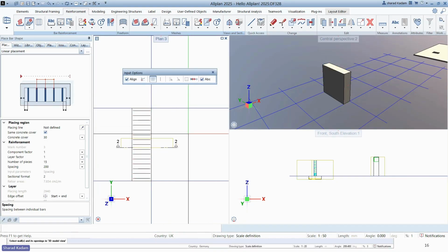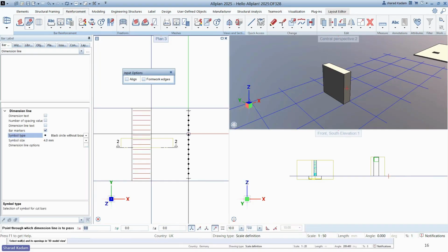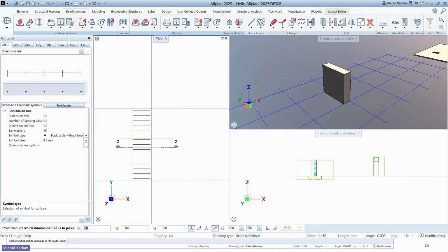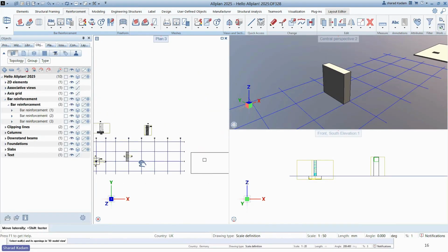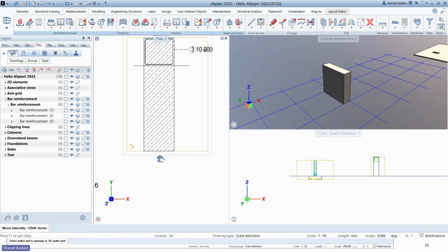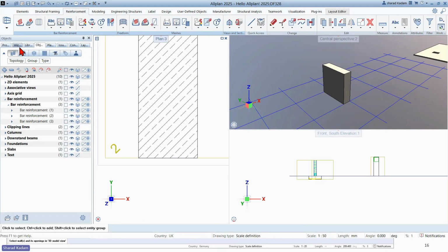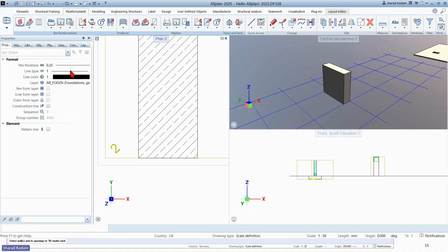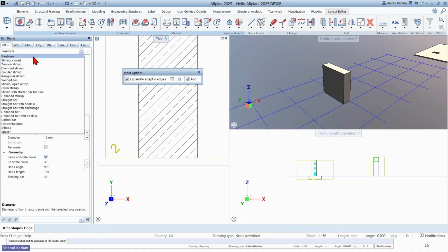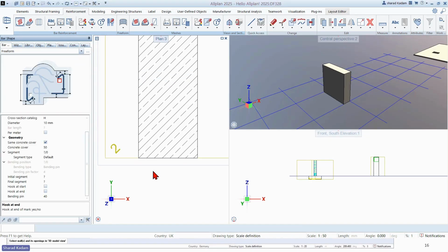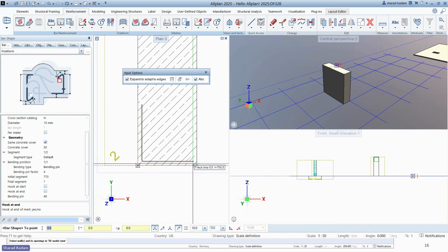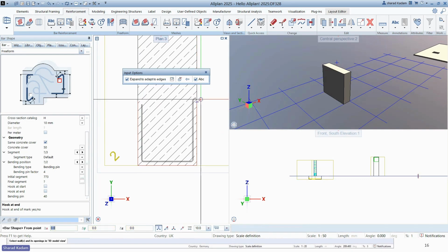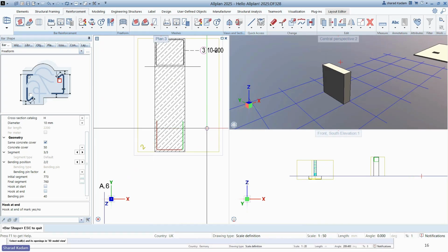So the best part of it is that we don't need to rely on freeform modeling or manual picking. But if manual picking is needed, then even that is feasible. Let's say I need to add some U bars at the bottom. We can use the normal default options available, as well as the freeform option. The freeform option is basically for wherever I'm picking, it will add the rebars to that particular location. So like this, we can do the freeform modeling.